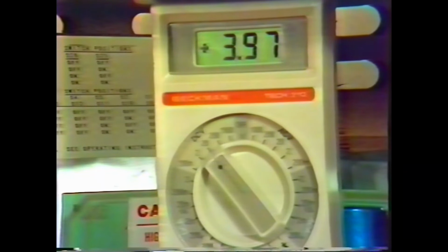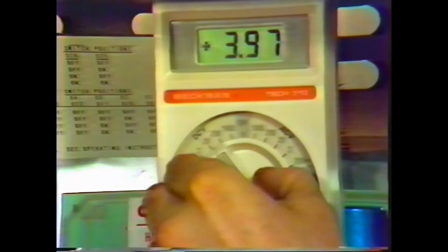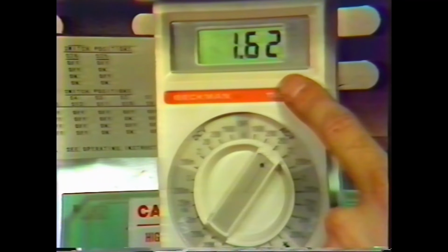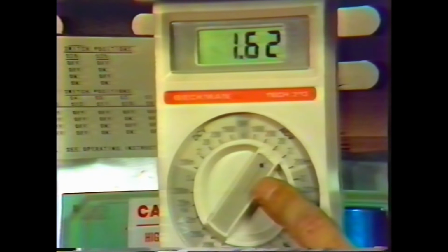When the voltage reads too low on your meter, switch your meter to read AC volts and look for that AC ripple. In this case, 1.6 volts of AC ripple riding on top of the 5 volt supply means that we have a ripple problem here, usually caused by a bad capacitor. In this case, though, we can trace the problem to a broken wire. The broken wire disconnects the capacitor and allows excessive ripple into the supply.